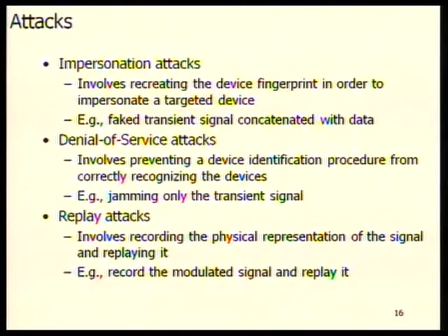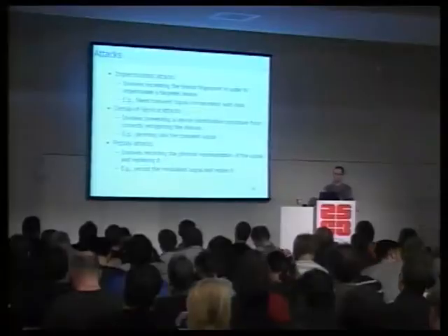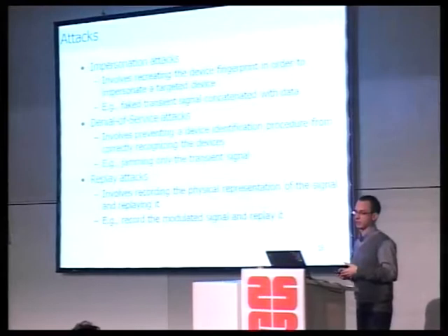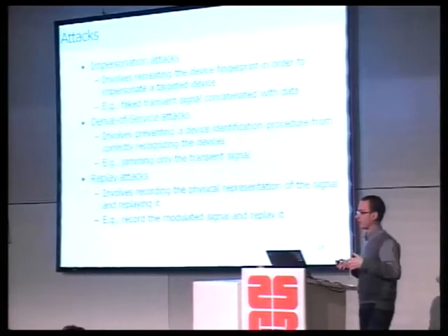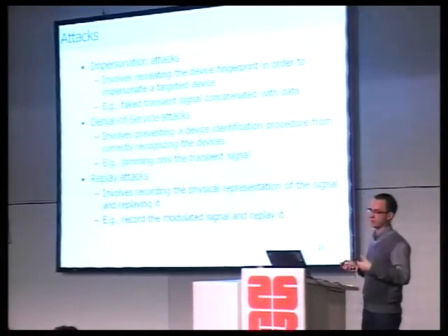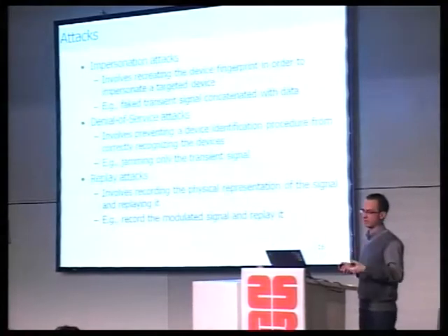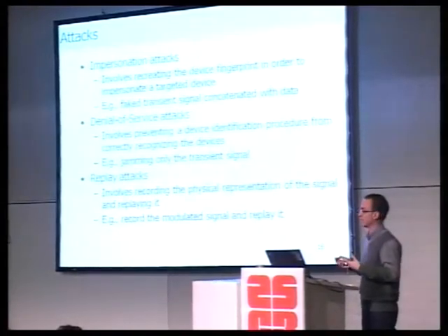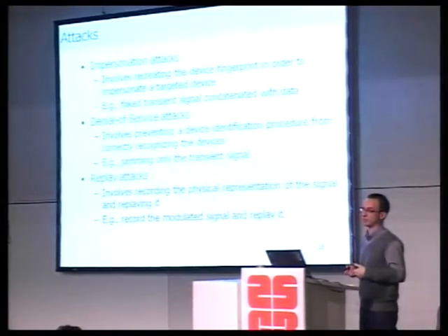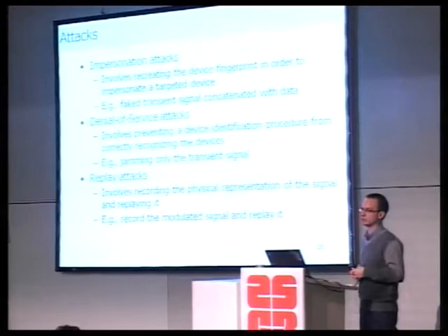The second thing we did was to see how the shape is influenced by wireless jamming attacks. There we were able to jam the signals at the beginning, and this also prevented fingerprinting because the shape of the signal was changing quite a lot at the beginning. As long as there is interference from some other device, this method fails to recognize the device. This can be used, for example, by an authority to prevent fingerprinting of devices by sending regular specific signal interference on the channel.